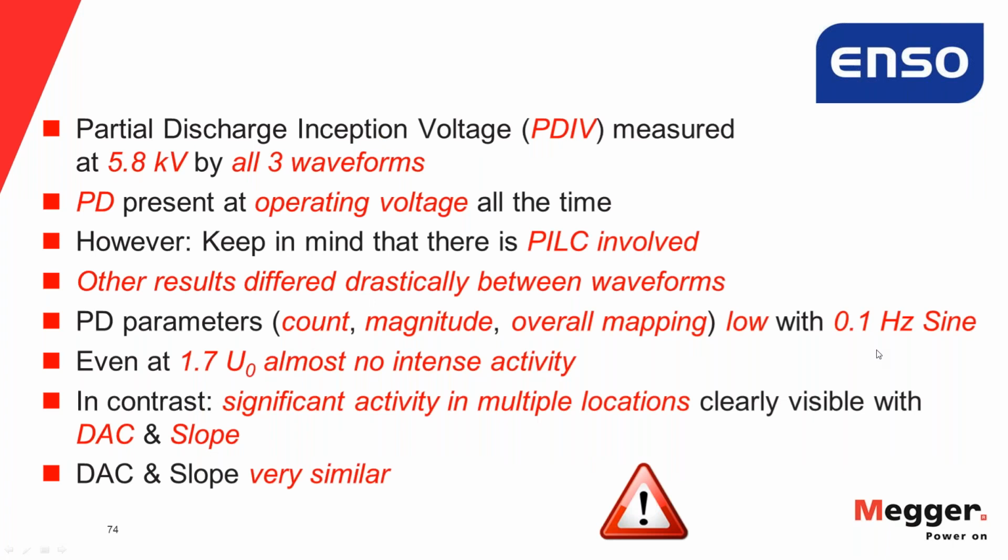Keep in mind, PILC is involved, so the results will always be kind of different, because pretty much any PILC cable these days in Europe will have partial discharge on it because they're so old. The fact that they can tolerate that lies in the fact that the insulation medium is a fluid and not a solid, so it's not deteriorating that quickly and that harshly, because it's partially self-healing. To a certain extent, a fluid is self-healing.